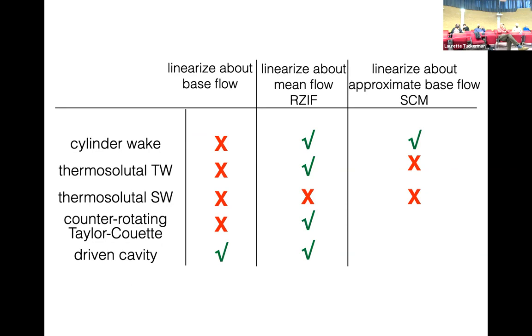It works for the cylinder wake, it works for the thermosolutal traveling waves, it doesn't work for the thermosolutal standing waves, and it works for counter-rotating Taylor-Couette and driven cavity. And now we try something, another approximation. You approximate the base flow, so that's SCM, and that works for the cylinder wake. You saw all those things that Kelly's group got there. And it doesn't work for either of the thermosolutal cases, obviously not for standing waves, but not for traveling waves either. And I'm sorry I went over, and I'm sorry I had problems with my mouse. There, thank you. Right.